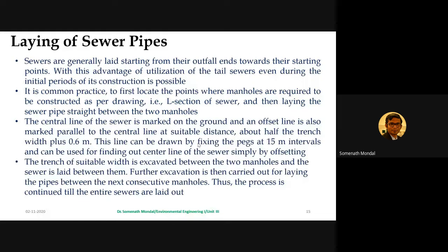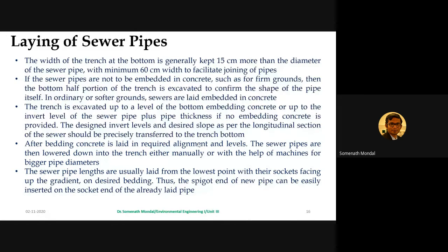Further excavation is then carried out for laying the pipes between the next consecutive manholes, and you basically keep on continuing this up to the highest point. Thus, the process is continued till the entire sewers are laid out. So this is the entire sequence which I wanted to mention.